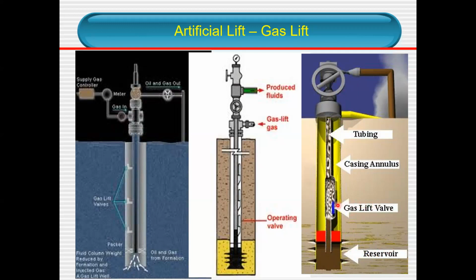But with the gas lift inserted here, and enough gas, probably you can jump from 200 to 500 if there is enough gas being injected into the tubing. These are the produced fluids which are coming from the tubing. Gas lift here is injected through one of the valves, which goes into the casing or the tubing that is surrounding the main casing. And these are the schematics, as you can see here. They are showing you different diagrams for you to understand better.